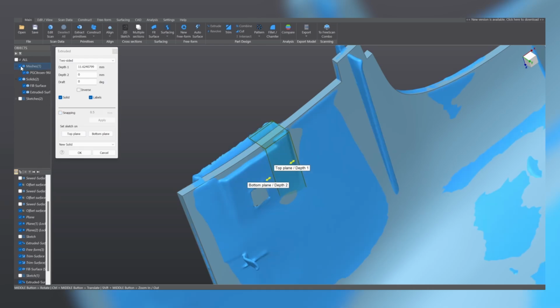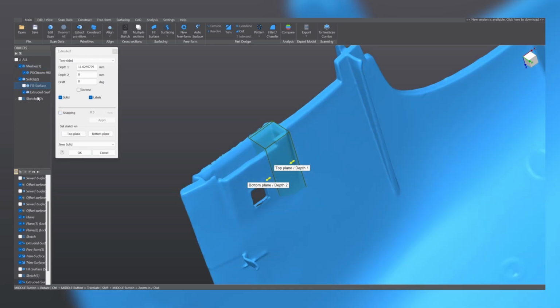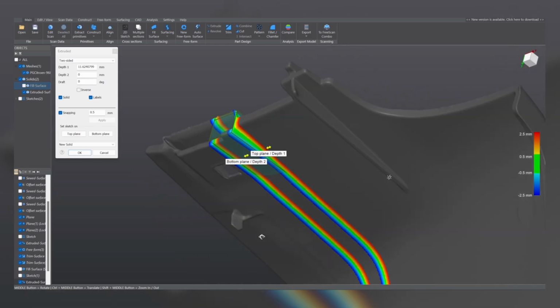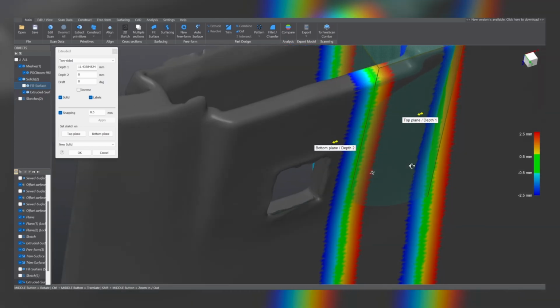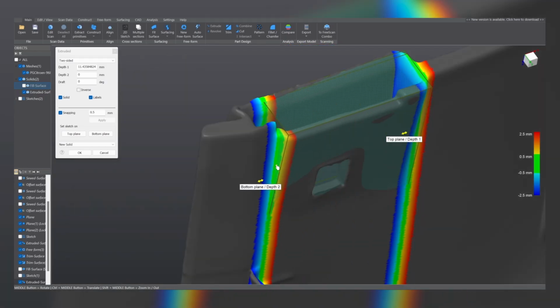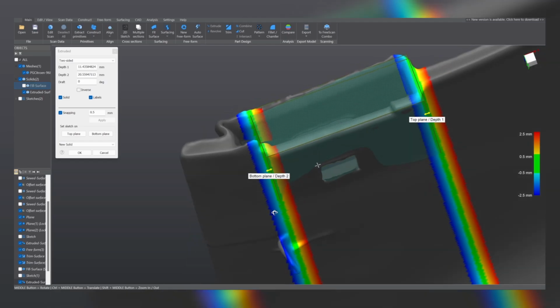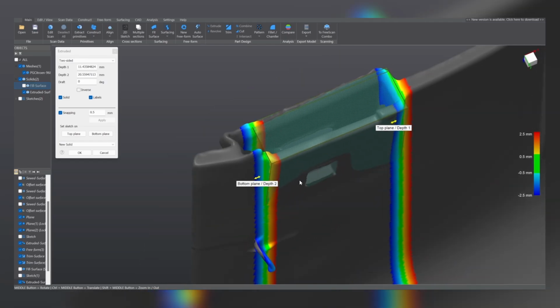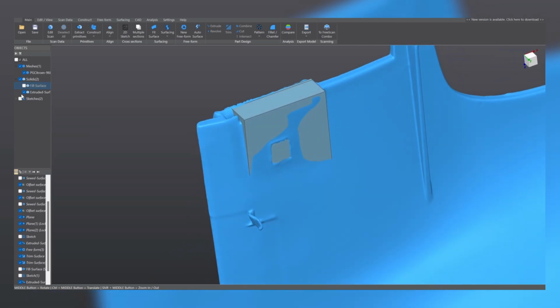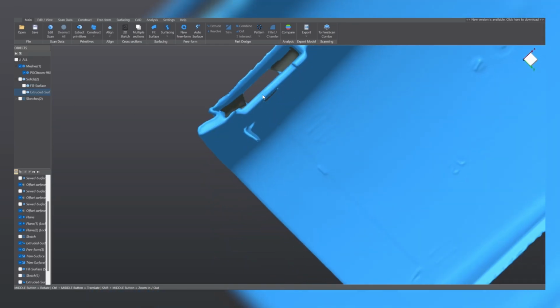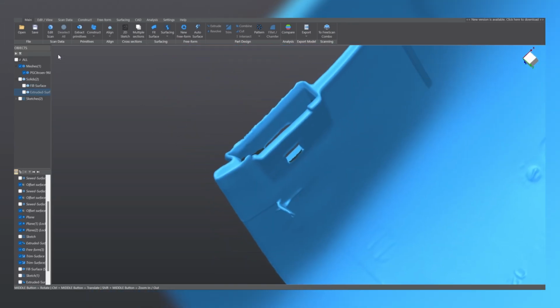Now, with the mesh displayed and the snapping tool on, we can select directly on the mesh the extension of this extrusion. And we are going to use these two walls here. Make sure that new solid is selected and click on OK. Now we have our basic solid, and we are going to tackle now the cuttings. To do the cuttings, we repeat the process.